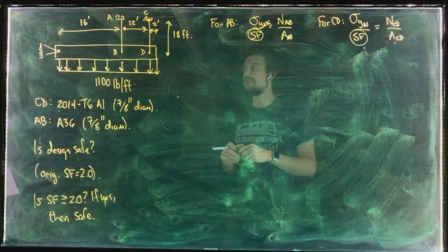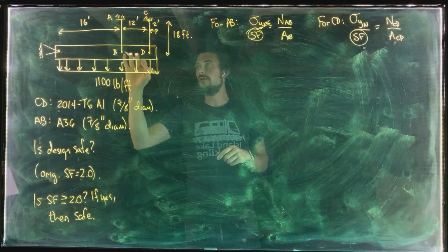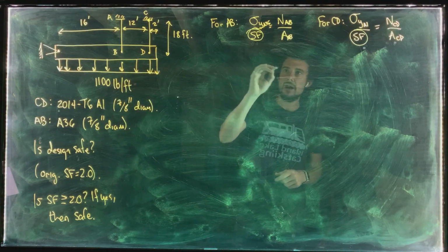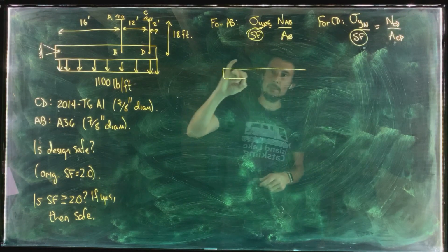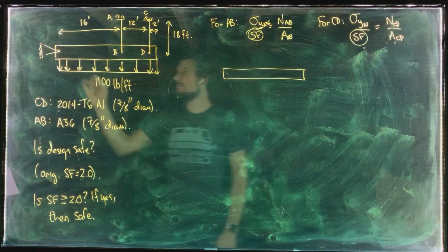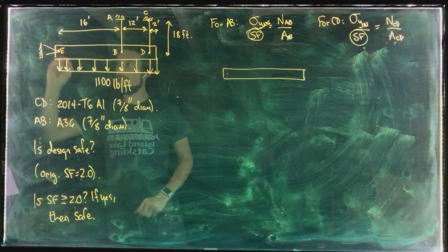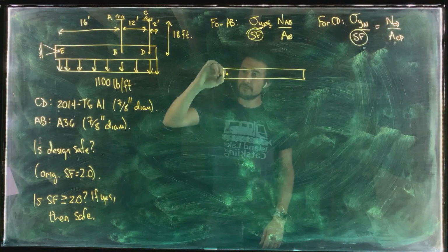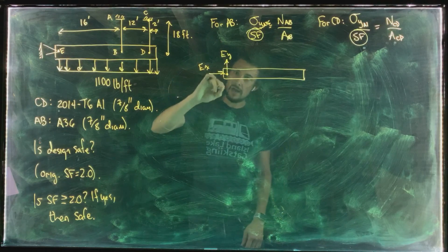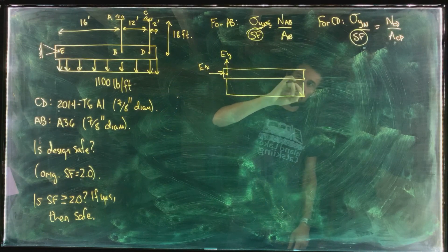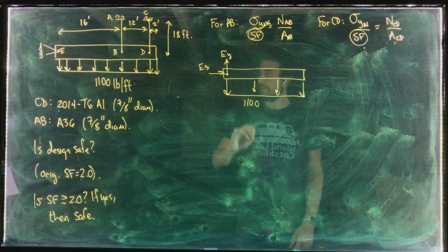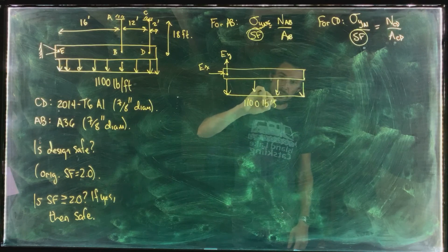Okay. So in order to find the normal forces in those two cables, it would help to draw a free body diagram of that horizontal member. Okay. So here we go. We've got the pinned point, A, B, C, D. Let's call that point E there. So we've got EX here, EY. We've got our distributed load. Okay, we know the value of this, 1,100 pounds per foot.